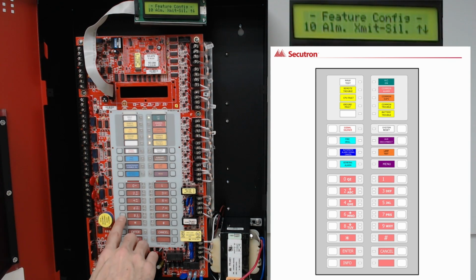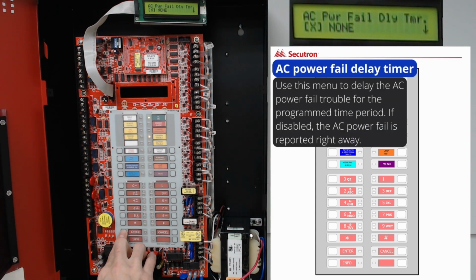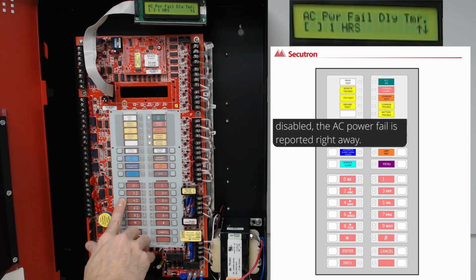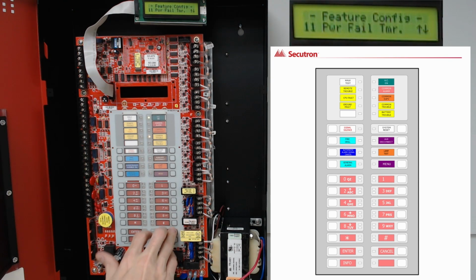The next option in Feature Config is our Power Fail Delay Timer. By pressing Enter, we get to see the options for the AC Power Fail Delay Timer. By default, none has been selected. By pressing the down cursor, we can scroll through some of the other options. We have 1 hour, 2 hours, or 3 hours. If we see the desired duration, we can hit the left or right cursor arrow to apply the X, and then Enter and Cancel to go back out to the previous menu option.